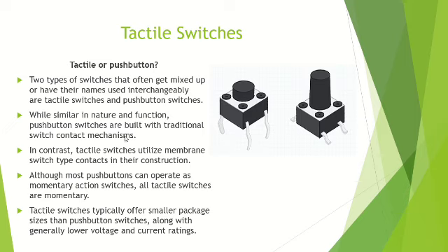While similar in nature and function, push button switches are built with traditional switch contact mechanisms. Tactile switches typically offer smaller package sizes than push button switches, along with generally lower voltage and current ratings.